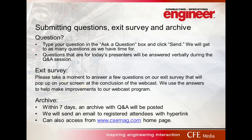But then to actually make that happen, like in an operating room, for example, where you might have a code minimum of 20 air changes, but the load might require 30, and sometimes you want the air quantity to be able to vary and the room to stay positive. You also might have a night setback sequence where you might go down to 6 air changes at night. You want the room to stay positive in all of those scenarios. So the best way to do it in that case would be to have high precision air terminal units, like a Venturi valve or something like that, where you have a tracking pair of supply and return valves that go up and down together and maintain the same offset.